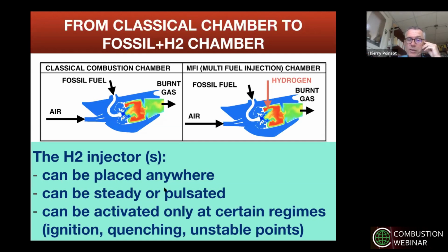Let me just mention that the combustion experts in the room will certainly say, whoa, careful, you inject hydrogen here, you will have diffusion flames, and you will make NOx. And that's actually one of the big problems in these technologies: if you're not careful in the way you introduce the hydrogen, you will end up in a situation where you produce a lot of NOx. And this is where combustion research is needed again.